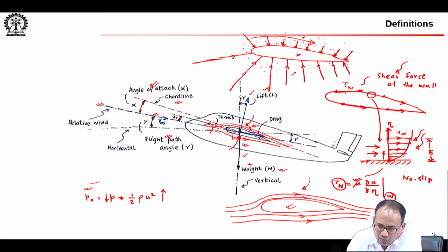So, that way if you run this thing at every point, you can find the shear stress at each of these locations. So, here you have a distributed normal force, here you have a distributed shear force over the airfoil surface. So, if you create the resultant force, it will look something like this.